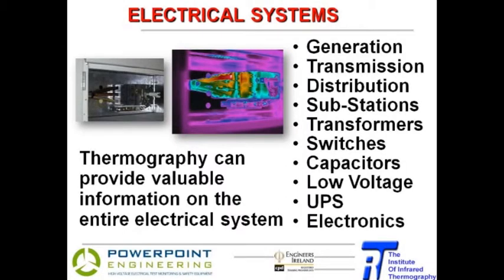With electrical systems, obviously thermography can provide information on the entire system. Everything from generation, transmission, distribution, all the way down to the plus or minus 5 degrees that you would have in a laptop. You can use thermography and find useful information about that object or that circuit. Obviously, we need a current flowing, and in an ideal world, when we're doing electrical surveying, there'll be at least 60% load. Normal conditions, but at least a 60% load, because obviously as the load increases, then the temperature is going to increase.